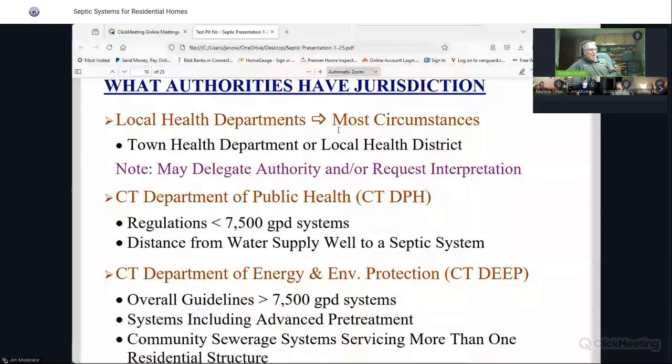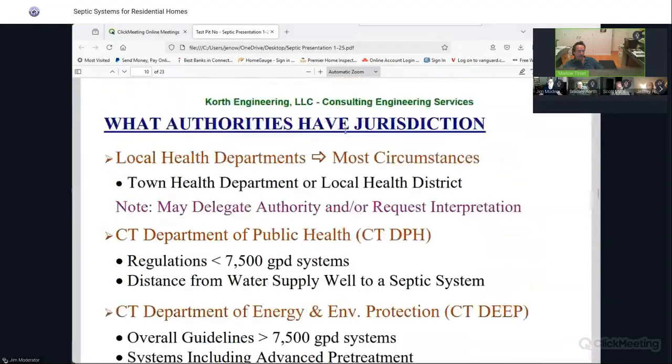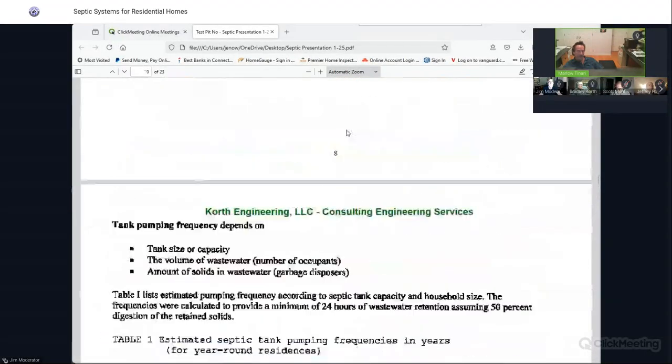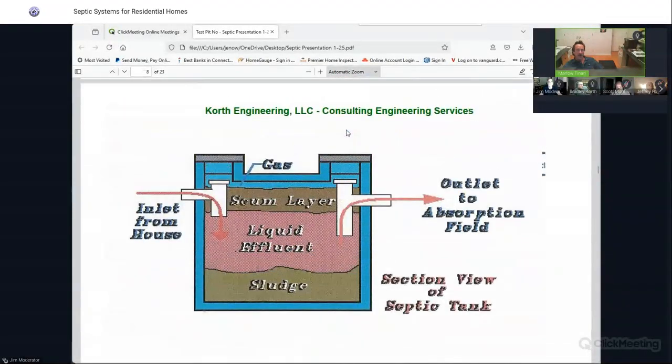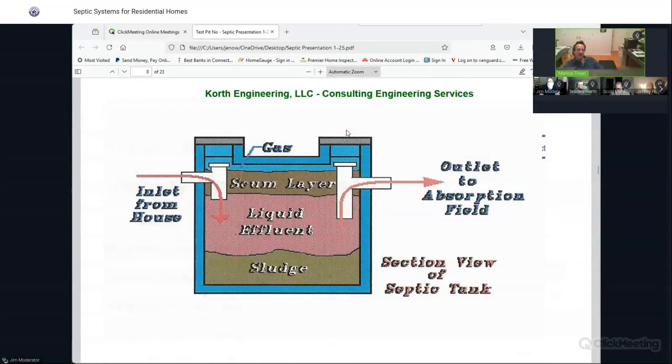Well, one other question I had when you showed the diagram of the tank with the scum layer and the sludge. There were some concrete tanks we were seeing recently on inspections that were being eaten up, and it wasn't because of bad concrete, which could have gotten into some of the tanks made back in the day, but it was more discussed about the off-gassing from the septic fields and so forth, making its way back into the uphill tank and the gravity system.